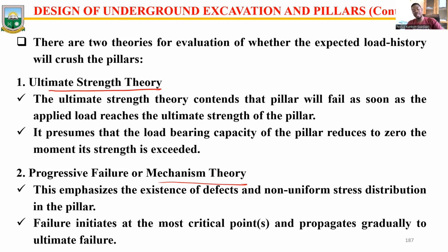So once I have a pillar, the pillar has a certain load it can bear. As soon as any load exceeds the strength of the pillar, there is collapse. And it presumes that the load-bearing capacity of the pillar just reduces to zero at that point in time. The moment you exceed me, I become zero and I can no longer provide support. That is the ultimate strength theory.